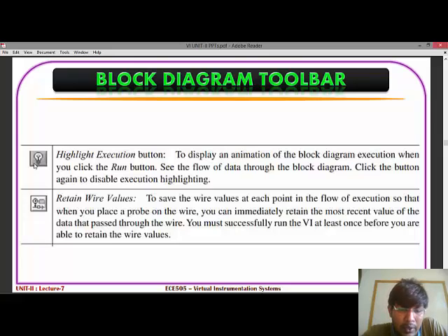At the output of a palette function, I can see what value comes out after the manipulation, and what output goes to the next part and the indicator. For continuous mode, different values are changing at that time. In my loop, in a particular iteration, which value is going on. This button is helpful for such information.